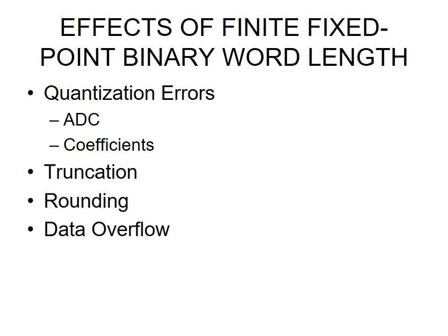In quantization errors there are two types, that is the ADC and the coefficients. Here we have mentioned the quantization methods: in DSP, the numbers and the coefficients are stored in finite length registers. So the coefficients and the numbers are quantized by truncation or rounding when they are stored, which is the concept of the finite word length effect.